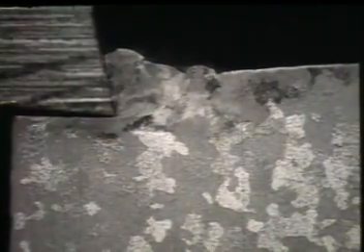The material now being machined is soft, commercially pure aluminum. The specimen has been over-etched to show the grain structure more clearly. Consequently, the black grain boundaries are not seen, but instead the individual grains appear as different shades of light and dark. As the tool moves through the workpiece, the plastic deformation in front of the tool and the flow of the chip up the tool face can be seen.